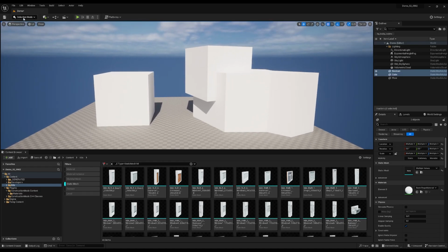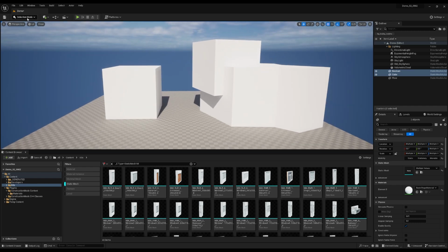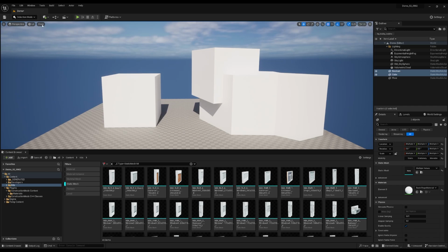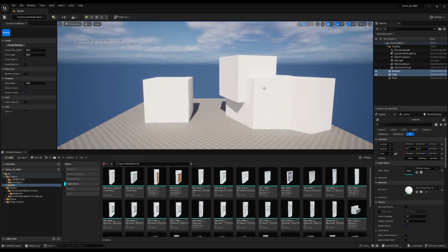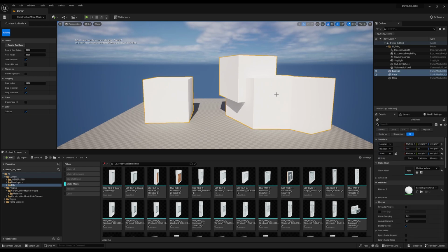First I will show you really quickly how to create buildings using the construction editor mode, and after that I will go into more details of the parameters and the tricks and tips on how to use it. So first, let's select the construction editor mode, let's press the building button, and in the scene we can select one or multiple buildings. Let's select multiple now, and I will create the buildings using this button.